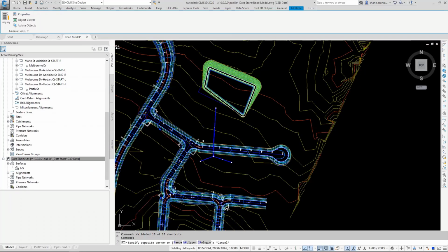Anyway, the story is you will get a symbol, the exclamation mark and the yellow shield. Basically, then you've got an option to repair, and you can go and find the original drawing, but you need to find the original drawing. See, mine has completely lost the connection. So my data shortcuts don't even appear anymore. And let's see if my alignments fail.